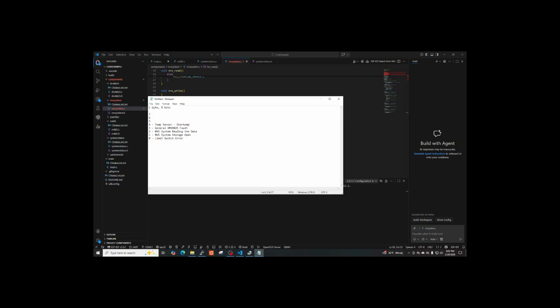Basically, if we hit that threshold, if it gets too hot, obviously the temperature sensor interface driver we write will operate the fan, but also fault out if it starts reading an over temperature condition of the board. We might want to then factor in other things that we could do with this.